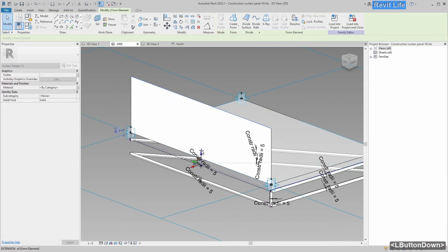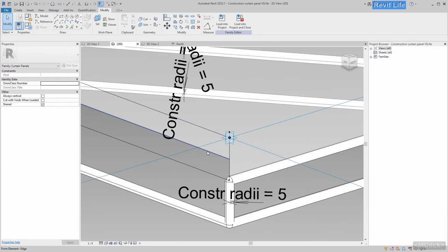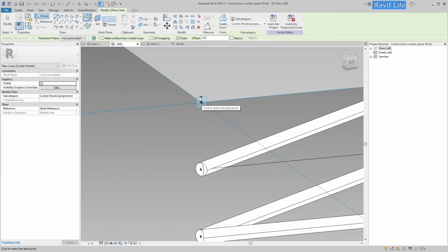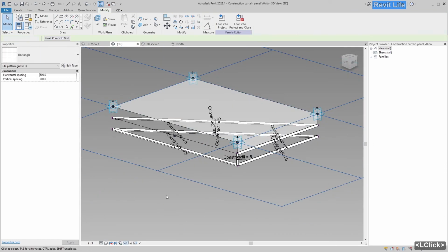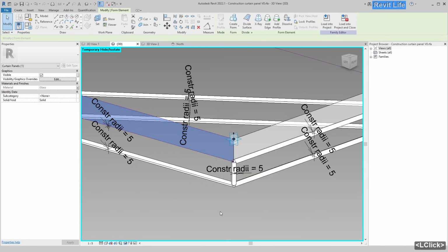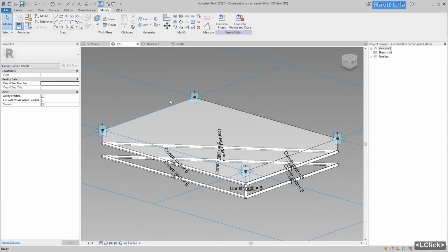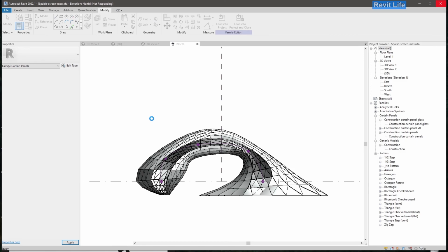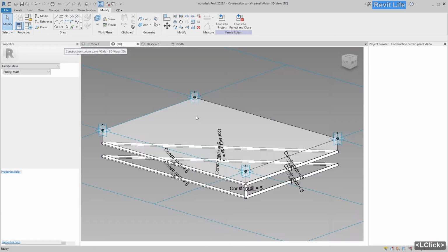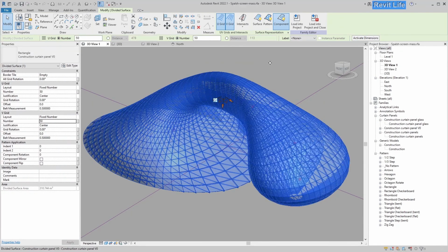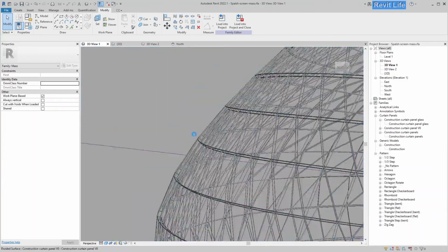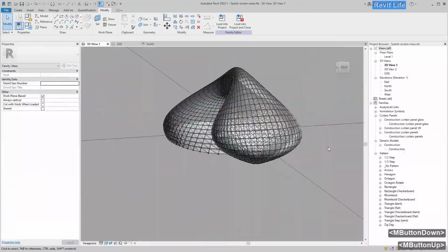So for example, it turns out that I cannot change the radius of the pipe by adding a parameter to the profile of the pipe, to the one profile that is in the middle of the model line. But that I will discover later. For now, I'm just happy that I can populate the whole surface without any errors. And here you can see that even the smallest of the cells are populated exactly as I want. And there are no errors and all the pipes are made.